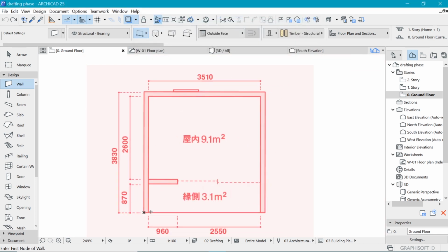So when you click the first point, you'll always see where the wall leans to. So here you have the option to change the reference. So when you click that, you can see it's being drawn on the opposite side. So now we can do that such that we create it on the other side. So let's put in the first dimension. So you don't have to do anything as long as you have this icon turned on, which is the snap guide points.